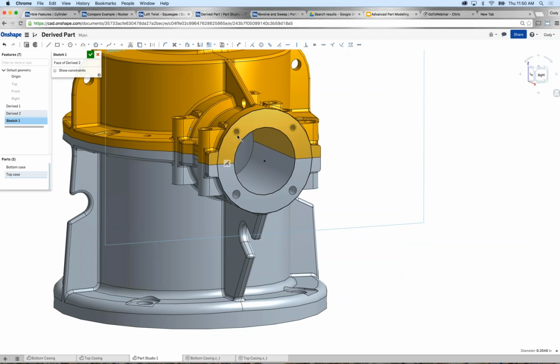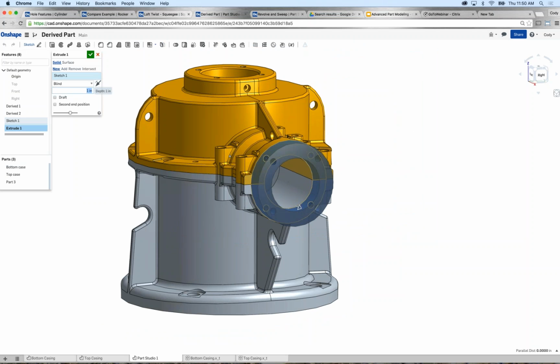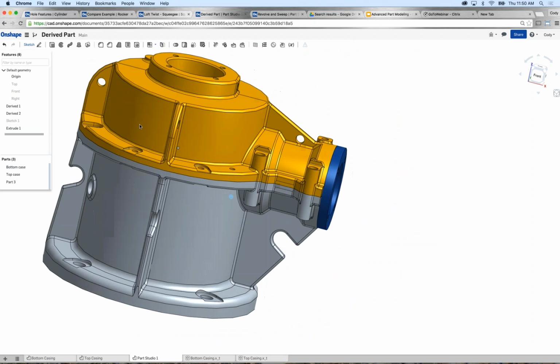So I can select all holes, select the use command, and convert that to sketch entities. Notice I didn't add one dimension. This entire sketch is driven by the parasolids that I've imported. And now I can extrude. We'll punch in 0.5, and I've built my simple flange.